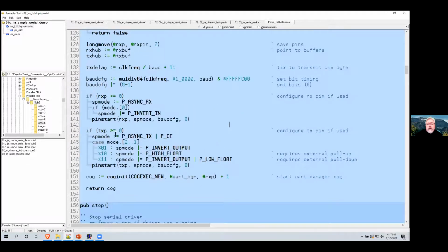And the same thing now with the transmit pin, there's a little bit more going on. It's a transmit pin, so we need to control the output, so we have to enable the output. Remember, smart pins are using the direction bit of the pin as an on and off control. So if we actually have to do output from the smart pin, we need to set that.